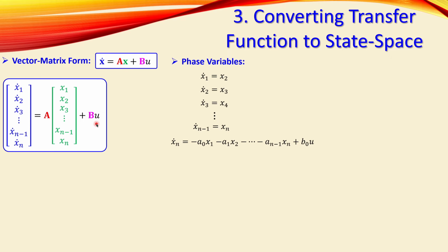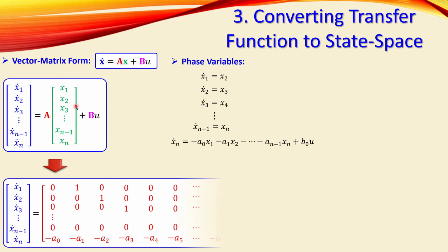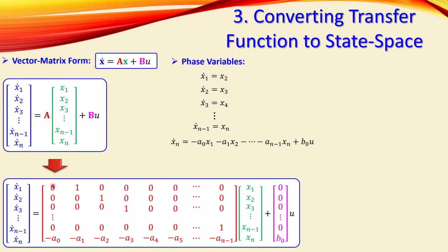And there's all the u and also the u. You can of course have 2 or 3 inputs depending on your system, and in this case we discuss only one input and one output. This can be then written in this form, in very general form, and that is just for phase variable format. We also discuss later the other representations like control canonical or observer canonical forms.